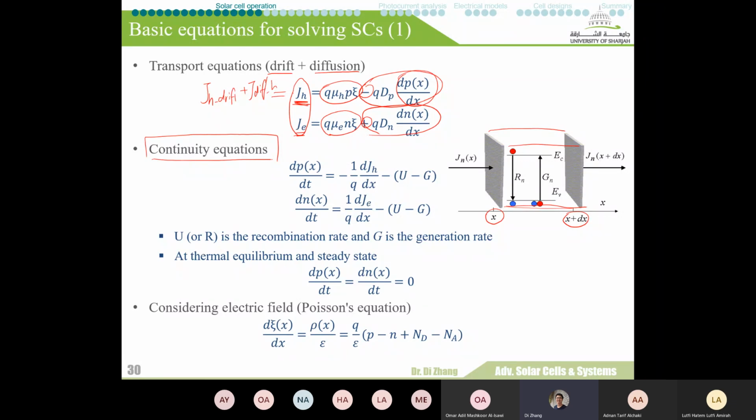Okay, the thing is that in the end, we count all the electrons that are going out and all the electrons that disappear, and then we also count how many electrons we are generating in this small volume, versus how many electrons are also going out because of the current. In the end, you have to make sure that the positive and the negative match. How many go in, how many go out, eventually they have to fit. You cannot produce electrons from thin air. You cannot make electrons vanish without any kind of phenomenon. So that is basically the concept for the continuity equation.